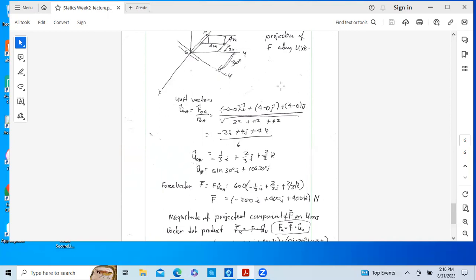There's a strength associated with that material. That strength translates to internal stress. Stress is force divided by area. And once you have that force and you know the stress, the unknown is the area. And as an engineer, you can size it. You can say what the diameter needs to be to get adequate area in this thing.